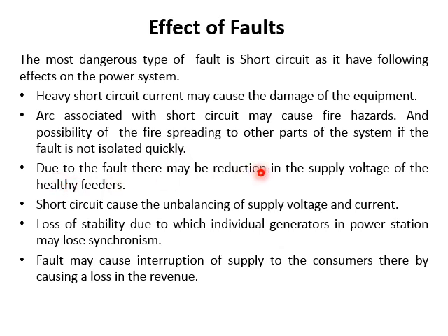Due to the fault, there may be a reduction in the supply voltage of the healthy part. Short circuit causes unbalancing of the supply voltage and current. There is a loss of stability of the individual generators in power stations, and they may not synchronize with each other.